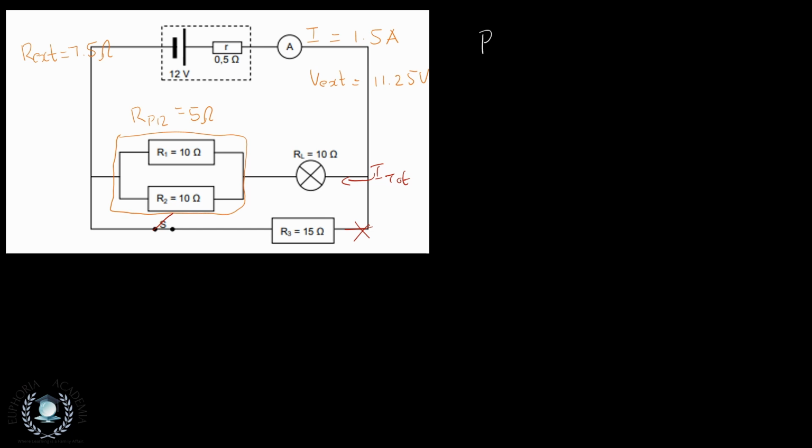We see that in the formula that power is equal to I squared multiplied by R. The current goes up through the light bulb, and the resistance is constant, so it stays the same. So the power dissipated has to increase. And how much more is this current?